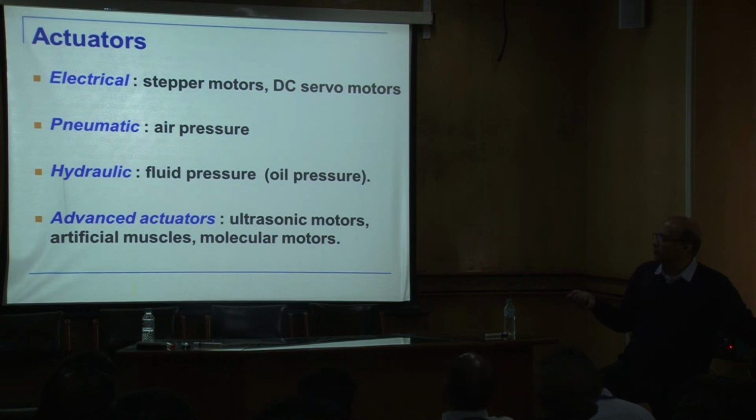The gripper is normally pneumatic, essentially because this piston cylinder mechanism or a pneumatic system is safe. If the robot were to hit something, if you have a motor, like you have a gear, this is not back drivable. You cannot drive it backwards. So if it hits something, something will break. Whereas a pneumatic system, a piston cylinder can just go back. So a lot of the robots today, which we call safe robots, are pneumatically actuated. All the robots interacting with humans and things like that, a lot of them are pneumatic actuated because they are safer.